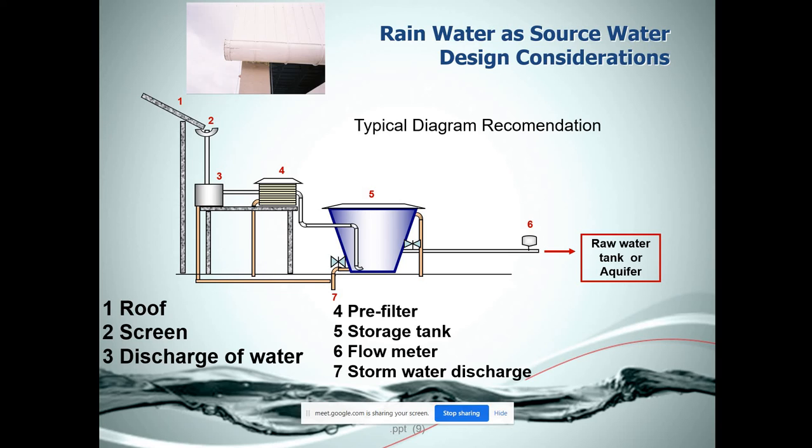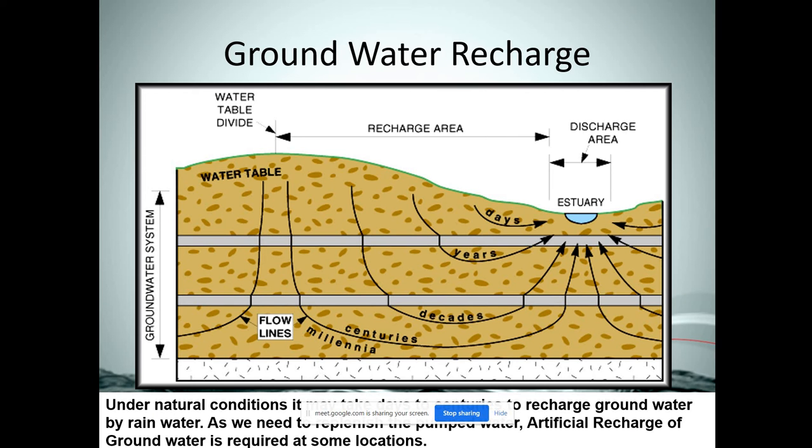Storage device may be either above or below ground. We can show in figure different types, including storage tank, water containers, lagoons, lined ponds, infiltration ponds, size based on rainfall pattern, demand, budget, and area. Percolation pit. To divert rainwater into an aquifer, the percolation pit is covered with a perforated concrete slab. The pit is filled with gravel, pebbles flowed by river, and sand for better percolation.